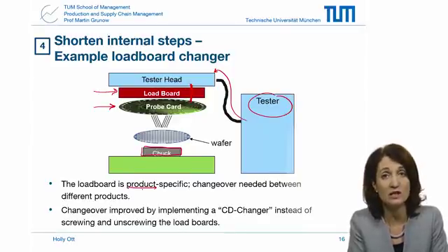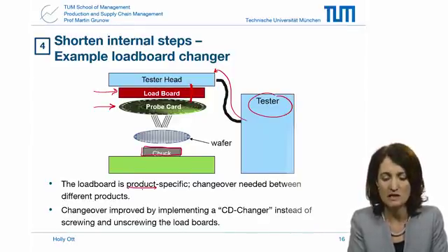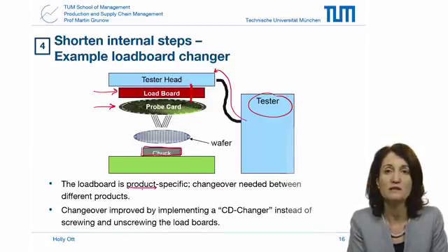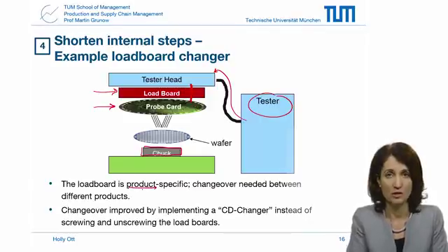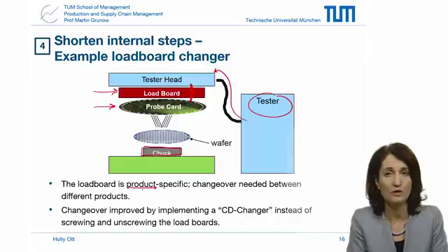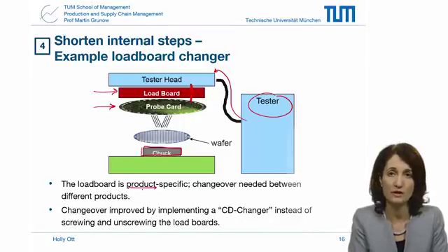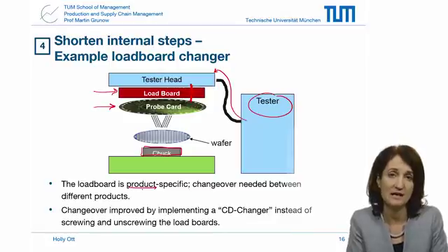Before, the load board was actually screwed into the tester head. So every time you needed to change it, you had to unscrew the screws. The improvement here was that they implemented a kind of CD changer type assembly, so that you would push the button, and the load board would pop out. You remove the old load board and put the new load board in, press the button, slide everything back in, and you could start the test.